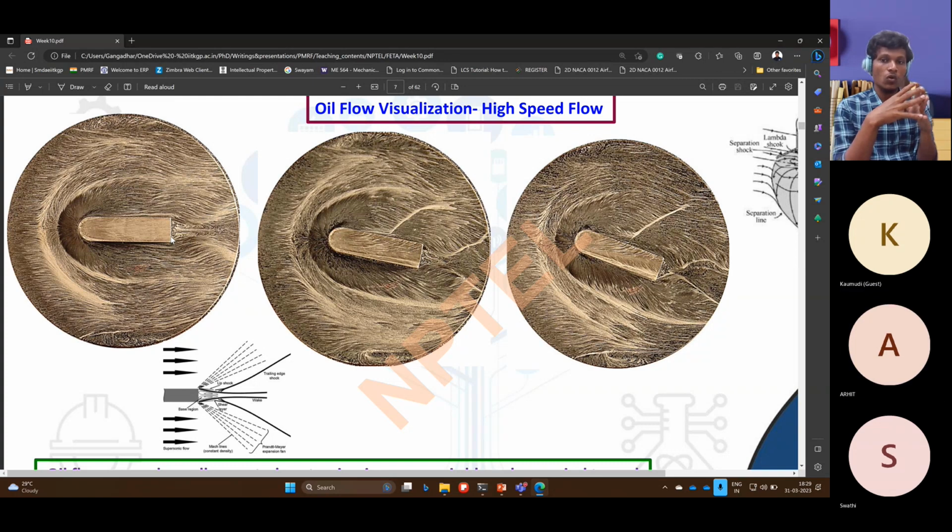Fine. All these things I am able to see here because your object is blunt. It is not sharp, it is very blunt. It is creating a bow shock because it is a supersonic flow, a bow shock some distance ahead of the object. So you are seeing the discontinuity in the oil as a kind of pattern.